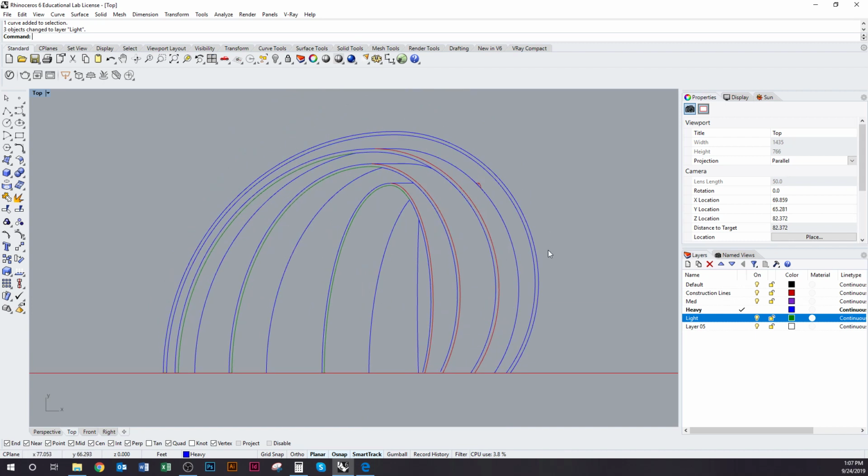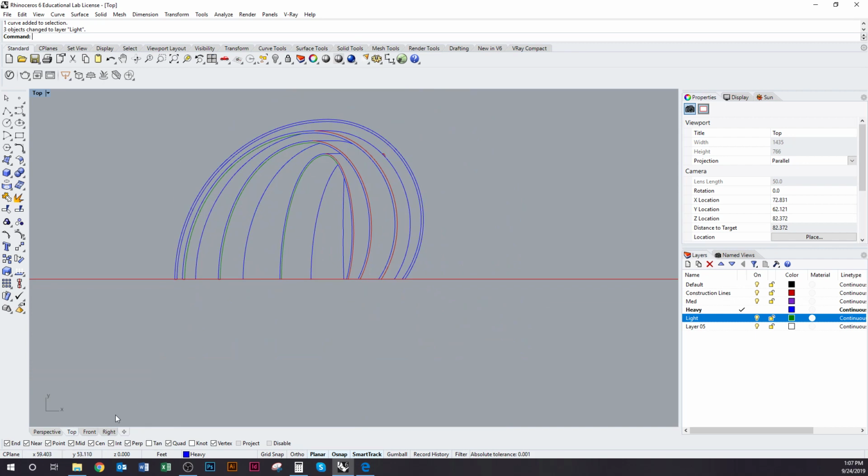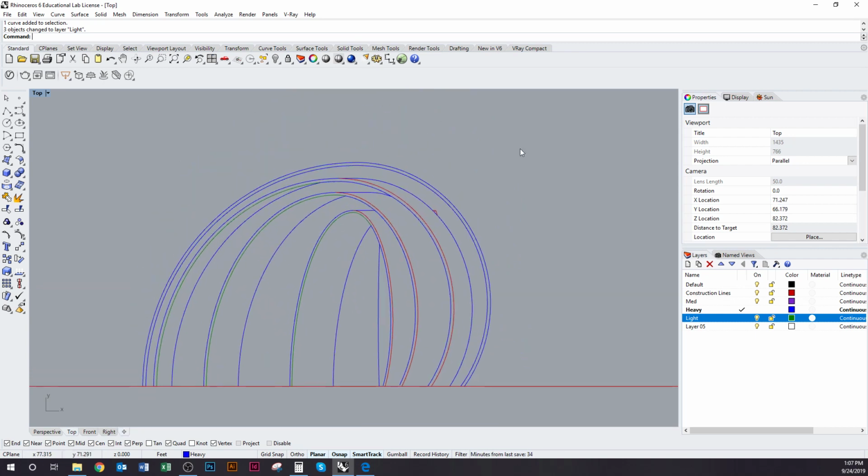Third layer, and build some hierarchy, some depth that way. Now, the way to really study whether or not your line weights are working, I think, is always to make a layout. Because, like I showed you, with shop drawings you can apply line weights and look at them in your viewport, but they won't be scaled. So what you always want to do is make a layout first.